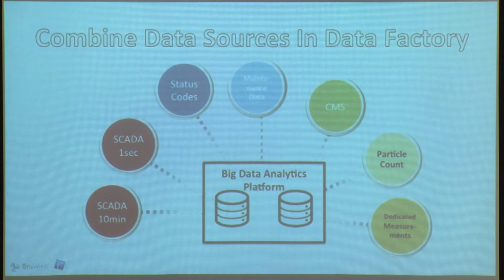The data that we collect is SCADA data, 10-minute data. This is about 400 parameters in the turbine. It's sensors like temperature, pressure, and so on, stuff that's not evolving too fast, such that this 10-minute data is sufficient. That's where it stops in most turbines.